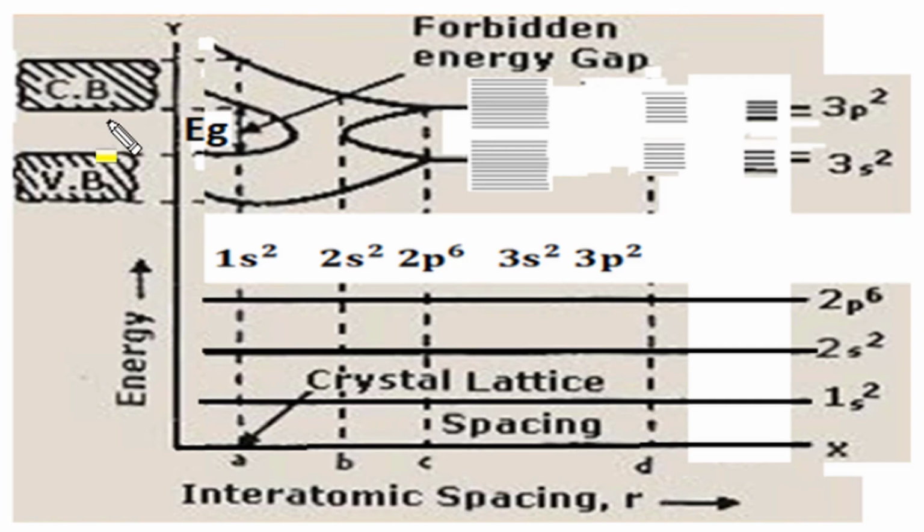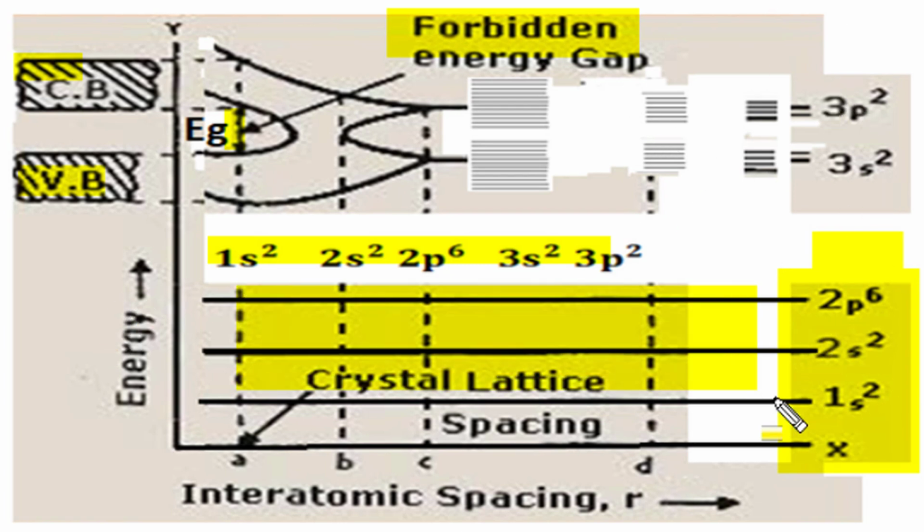We can explain the energy band diagram of silicon in terms of the valence band, the conduction band, and a gap in between the two, the forbidden energy gap. If we consider an individual silicon atom in the gaseous state, its inner orbital electron energy levels won't interact with neighboring atoms, so we will not consider inner orbital levels in this band formation, but the energy levels of outer orbital electrons interact with other neighboring atoms.